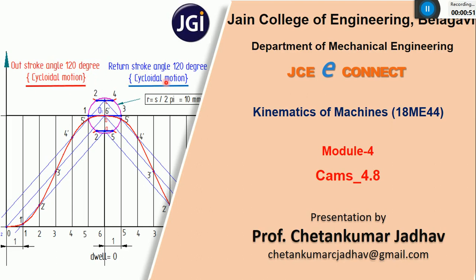Already in the introduction class, we have seen there are four types of follower motion. One is with a uniform velocity, one more with a simple harmonic motion, one more with a uniform acceleration and retardation motion, and the last one is cycloidal motion. This is the optimum motion of a follower in which the follower will be having a smooth movement. You can see over here there is no sudden rise or sudden fall. The follower will be moving smoothly during the outward and the return stroke, so that there will not be any vibration with respect to the follower movement.